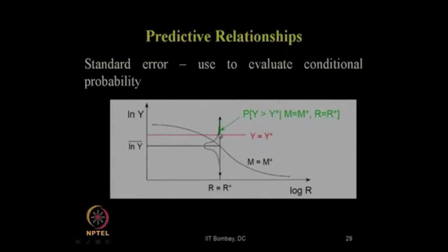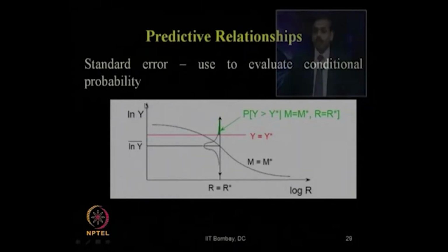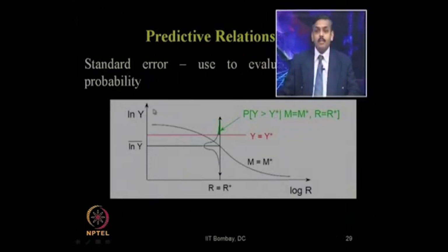Suppose this is the probability distribution function for any particular parameter, say as we have already mentioned, this is kind of attenuation relationship we propose in this form, like log of that parameter. It can be peak ground acceleration, it can be spectral acceleration, it can be peak horizontal velocity, various parameters which you are interested about. These are dependent on the log of r value, the distance. As the distance increases, they are going to decrease. That is nothing but attenuation, right.